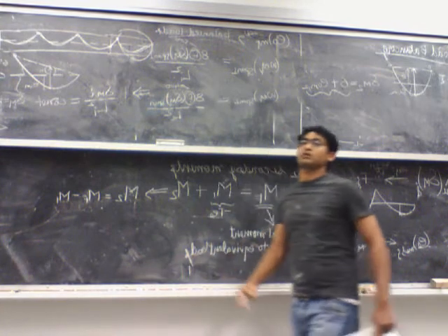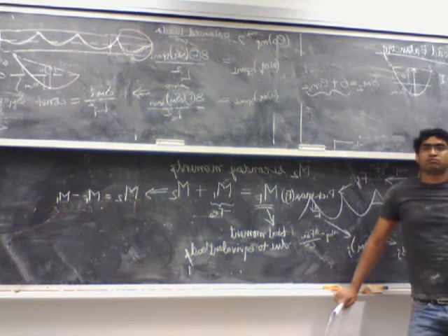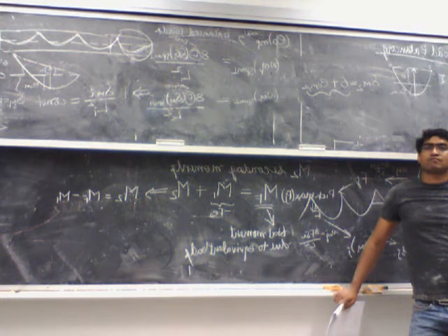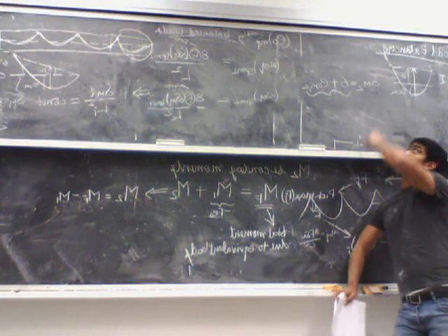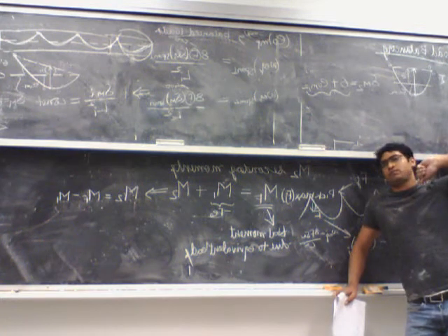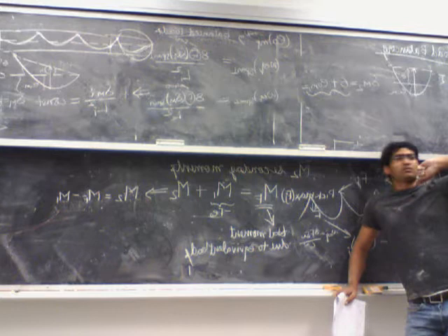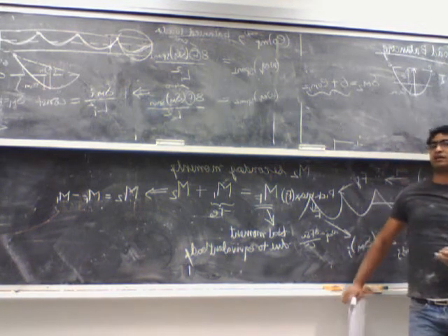Okay? Yeah. I'm wondering also, realistically on a test, say we're doing this part and then we finally create our tendon profile to balance the equivalent load. Do you think he would ask us to calculate the moments, like the indeterminate structure analysis? Yeah, why not? If you know moment distribution, anything which is a continuous beam with fewer than 3 or 4 spans should be straightforward. It shouldn't take you too long to actually analyze it.